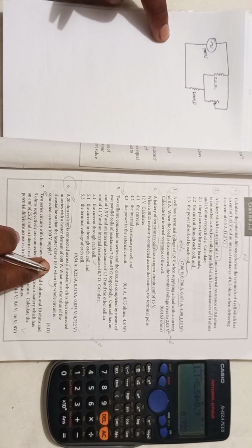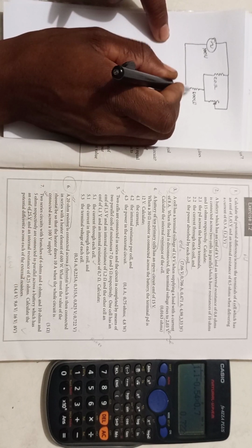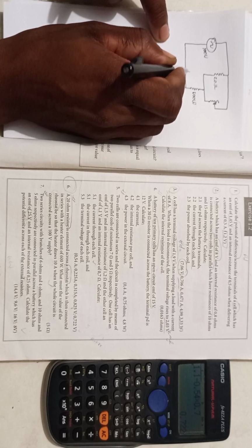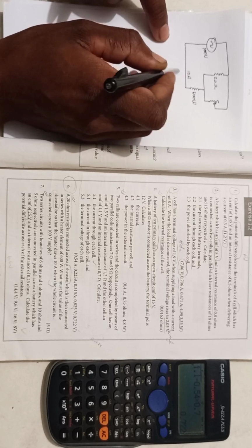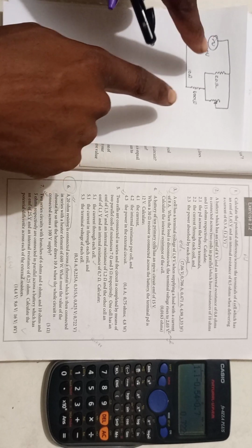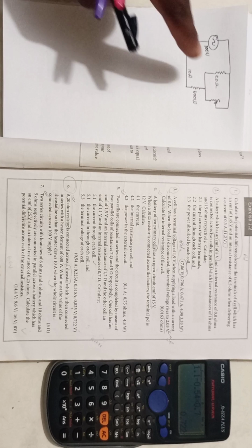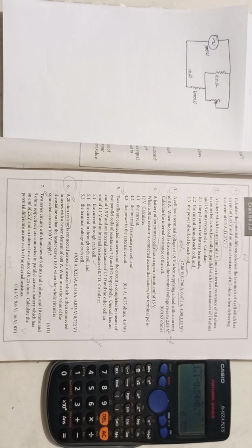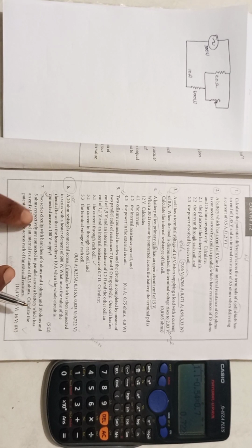So our current, they said a heater draws this current, so that means since it is in series with those, we have 10 amps current. This current is not the same as the current across there because the current will split there. Okay, now let us get what they want us to calculate.